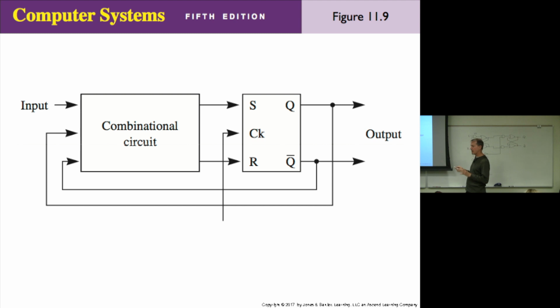As soon as this clock pulse goes up, depending on what S and R is, that should set the latch according to our rules: 0, 0, no change; 1, 0, set it to 1; 0, 1, reset it to 0, and so on, right? But not allow what to happen?